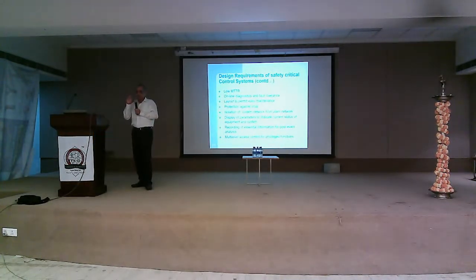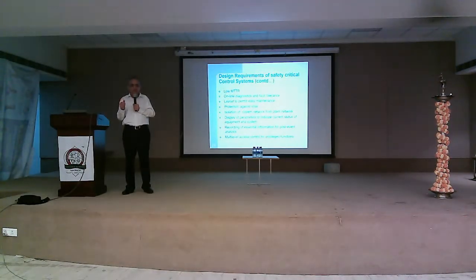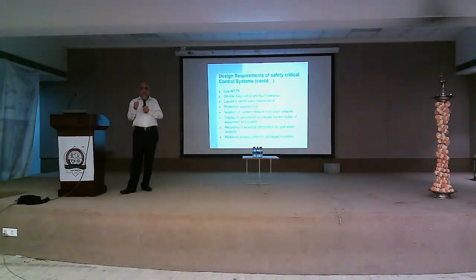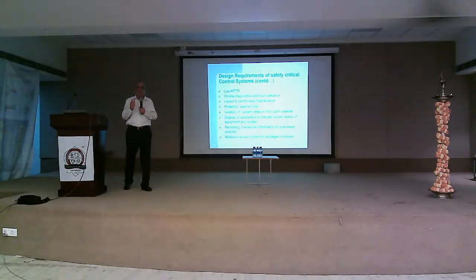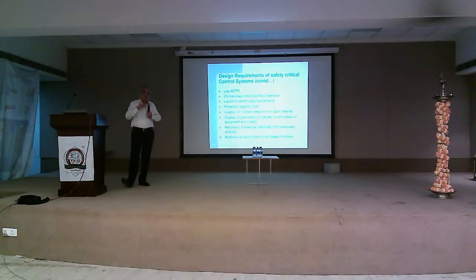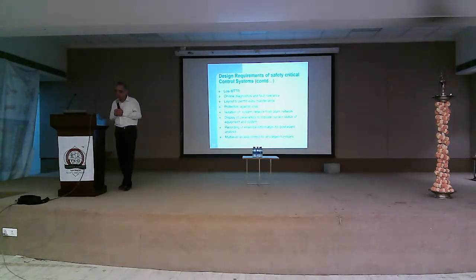So what we do, the power and ground pins are longer than the signal pins. When we put the board in, power and ground get connected first before the signal. And when we remove, the signal gets disconnected first. So this will not cause failure of the boards.